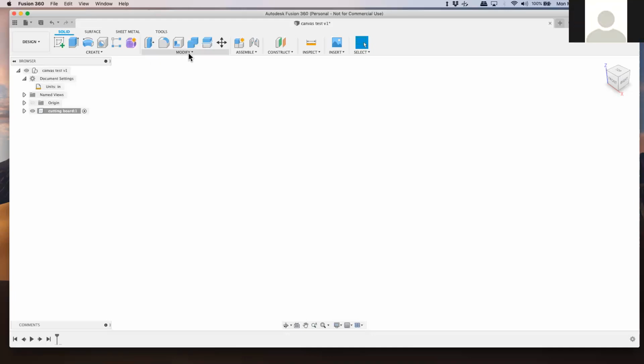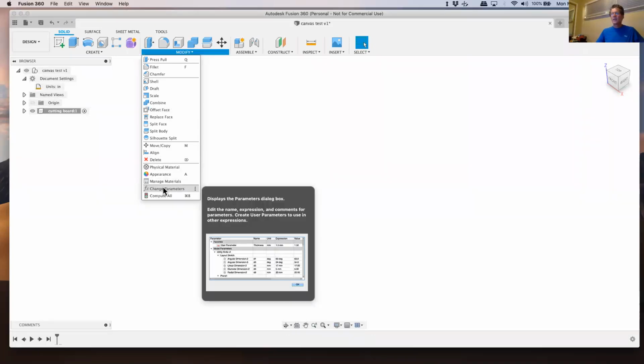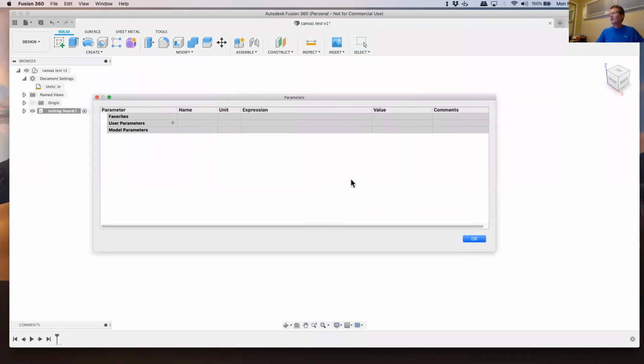The next thing we typically do, if we're going to do top-down design, is come in and define some parameters. It's a good practice. You don't always have to do it, but there are several good reasons for using parameters. The obvious one is to force us to do top-down design ahead of time and to use expressions, relations, and equations, so that the relationships between different parameters are appropriately expressed and calculated. And then we can go back, make families of products, and make changes quickly.